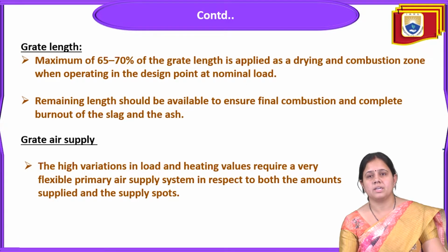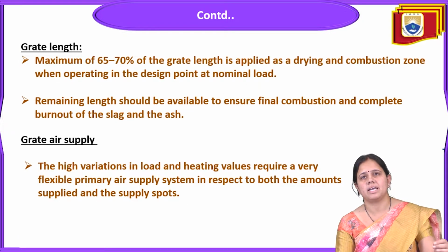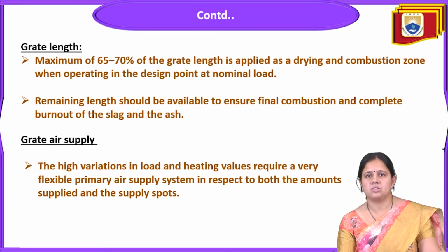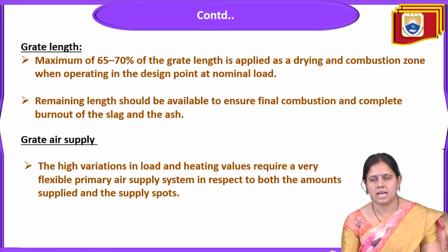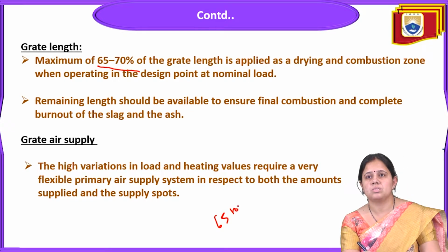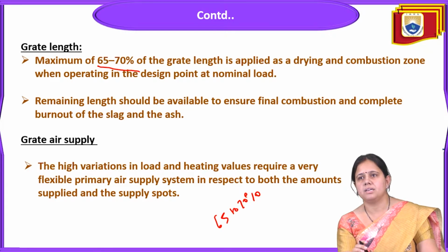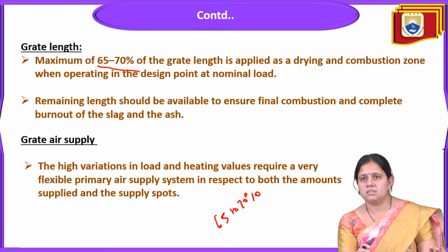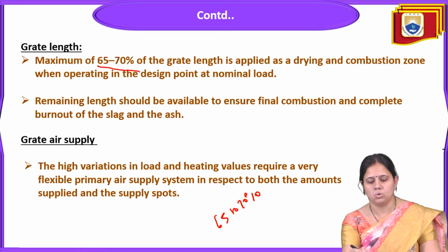Now we come to the grate length. How much length of the grate is required? A maximum of 65 to 70% of the grate length is applied as the drying and combustion zone, when operating at the design point at nominal load.